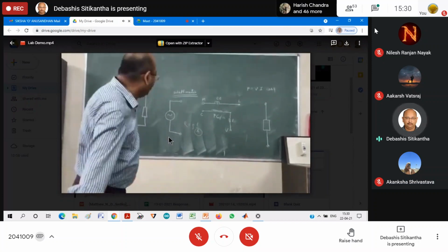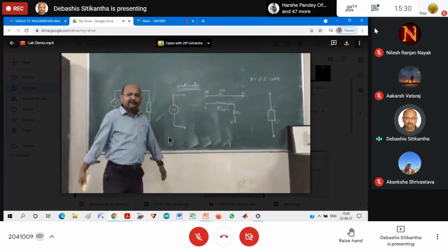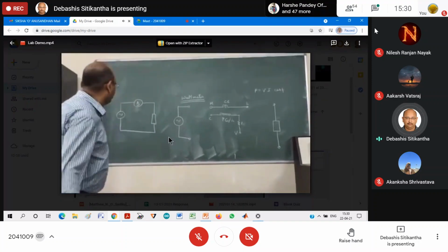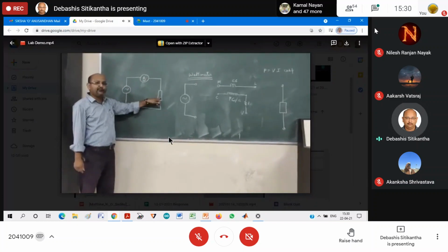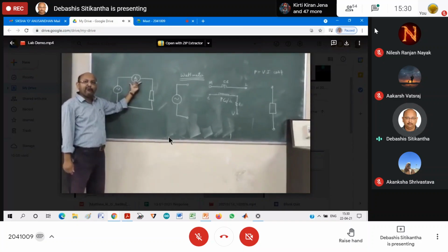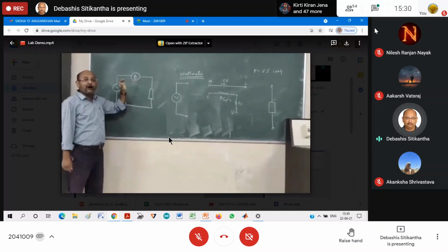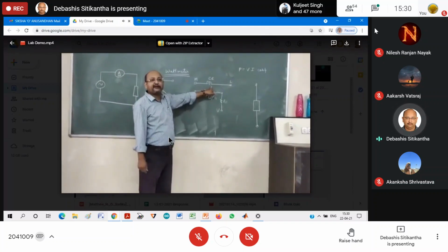So naturally, with less resistance to the flow of current, almost all the current is going to go to this load, so that it can measure accurately. So naturally I am using fewer turns of thick wire to manufacture this current coil.